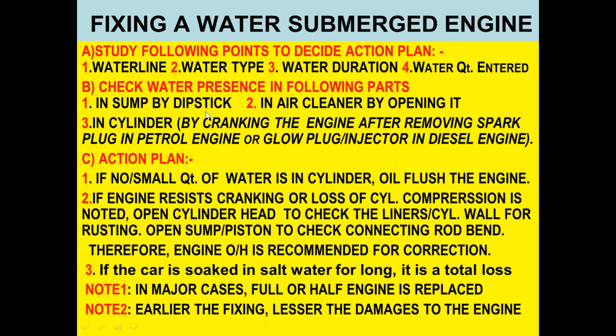Check water presence in the following parts. In the sump, by dipstick: you remove the dipstick and check for any water there. In the air cleaner, by opening. In the cylinder, by cranking the engine after removing spark plugs in a petrol engine or glow plug injectors in a diesel engine. What should be the action plan? If no or a small quantity of water is in the cylinder, oil flush the engine.